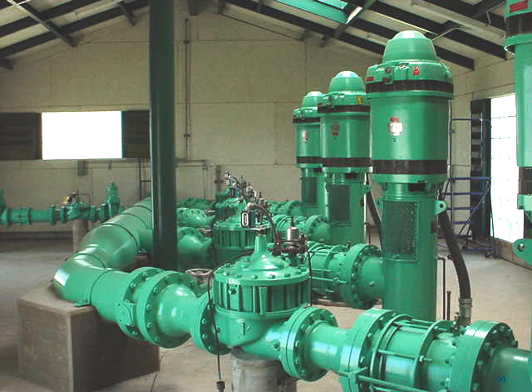It looks like down here in the back of this image, you've got another regulator. A lot of times, if your pump is running and it doesn't cut out once it reaches a certain pressure point, this will open up and either discharge into like a lake or somewhere, or it'll discharge back into the low pressure side and keep recirculating to prevent overpressurization. But otherwise, this is a really nice facility.